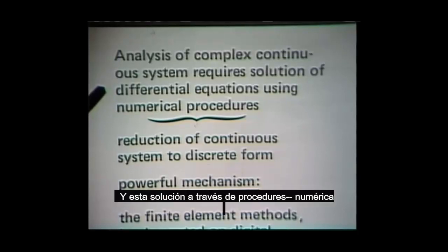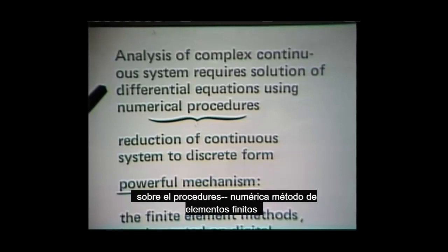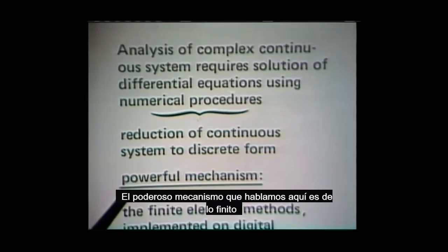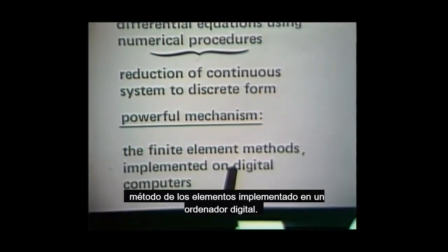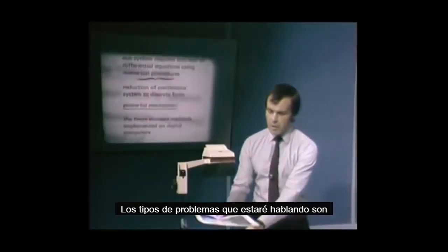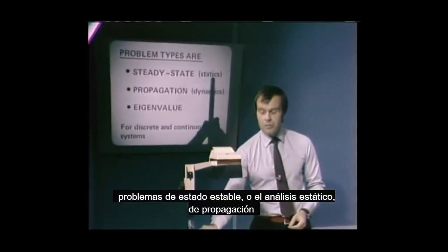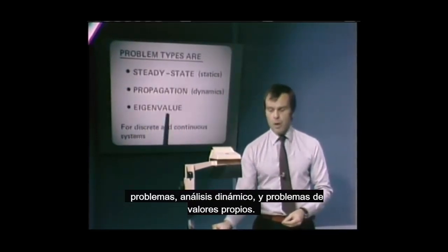And this solution via numerical procedures, and of course in this set of lectures we will be talking about the finite element method numerical procedures, really reduces the continuous system to a discrete form. The powerful mechanism that we talk about here is the finite element method implemented on a digital computer. The problem types that I will be talking about are steady state problems, or static analysis, propagation problems, dynamic analysis, and eigenvalue problems.